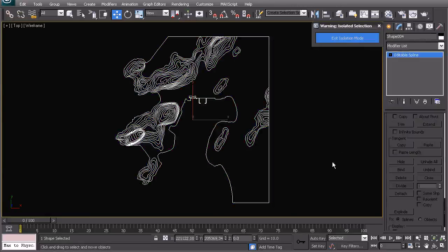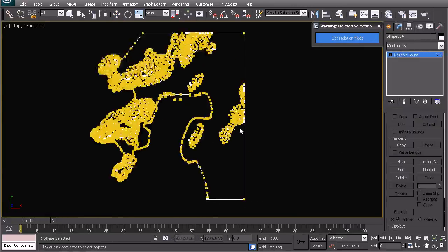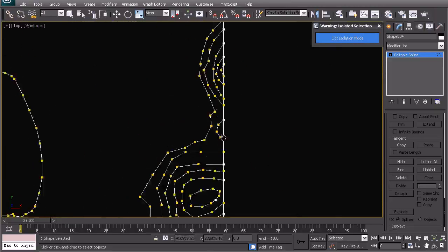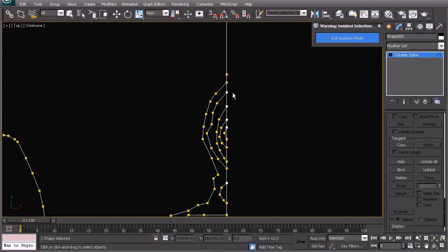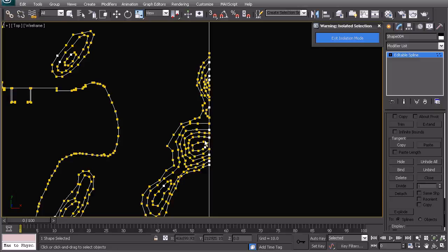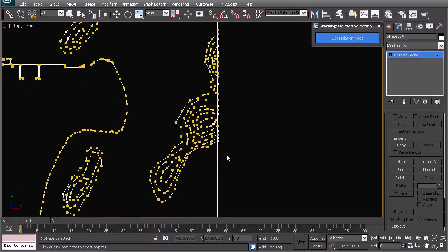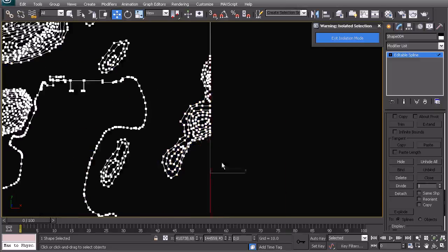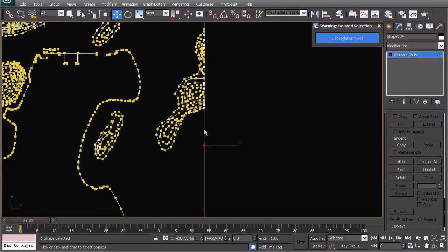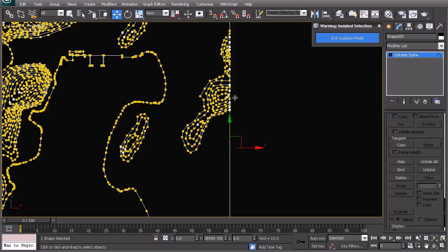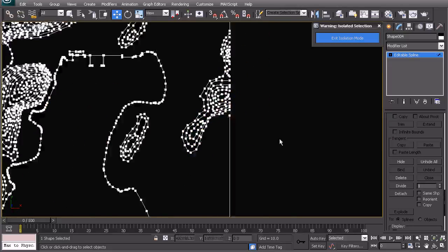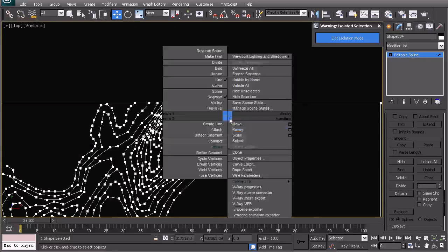And I'm also going to refine the edges a little bit so that we do not have the confusion of the line on the side here, which is saying 0, and right next to it we have, let's say, 200 meters. So that doesn't really work. So we will just do some editing here, create some vertices that we will then use to delete these lines.